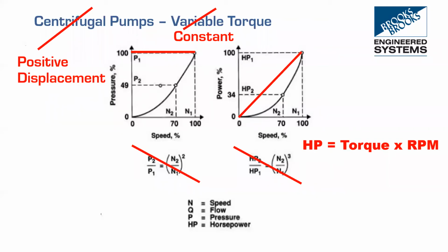But if you take that same motor and put it on a positive displacement pump, that VFD is now going to be undersized, and you'll be tripping the overload setting. So you would have to go up to the next size. Okay, I totally got it.